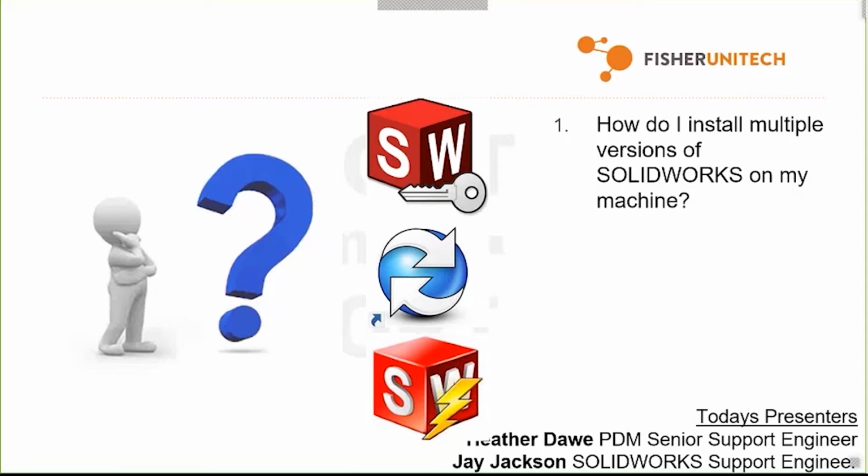So if my company were upgrading to 2019, they'd want to upgrade their Net License Manager to 2019, and I could still run SolidWorks 2017 and 2016 on my computer because the Net License Manager at 2019 can dish out those licenses.